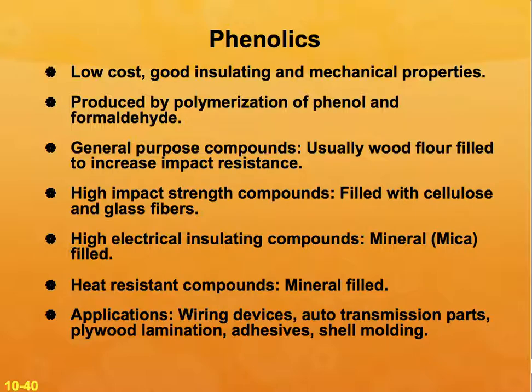You can also add carbon black to get heat resistant compounds, etc. So they have a number of different applications like wiring devices, auto transmission parts, lamination, adhesives, shell molding, etc. But essentially, anywhere you want really high temperature resistance is where you use phenolics.